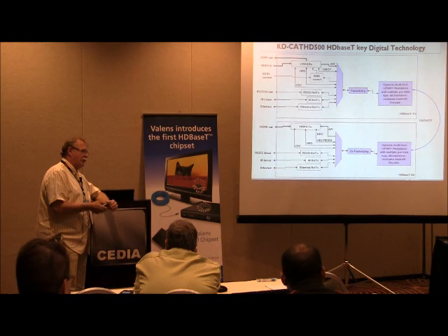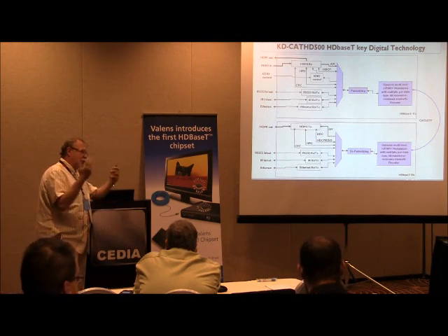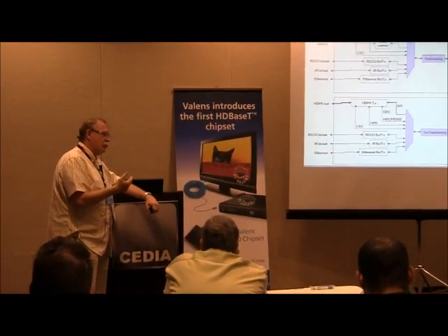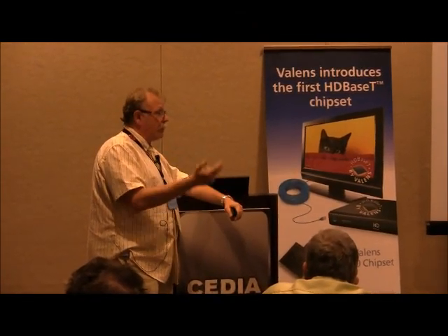An example is a TV that has 2 speakers, and that TV will probably request 2-channel stereo audio from the source. When the source device sees that EDID, it most likely will put 2-channel stereo on every audio output.